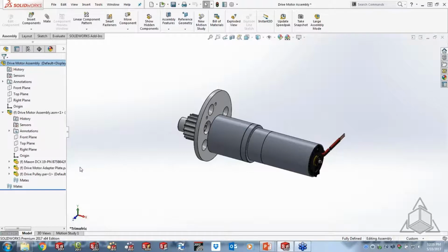The old way is translation. The old way is the software trying to understand all the surfaces and faces and put it together to create a solid model in a new, completely different format. The new way is for us just to be able to utilize the existing CAD data in its native format and point to it, just like adding an existing SOLIDWORKS file in there. That's all I'm doing, is inserting, in this case, a Solid Edge file directly into a model. Okay, so that's SOLIDWORKS Interconnect. That's how you turn it on.